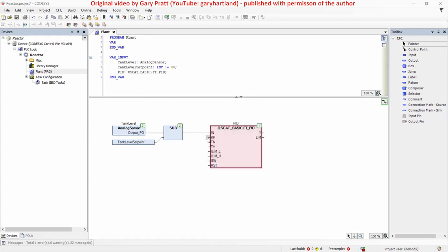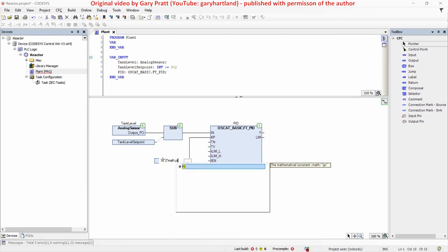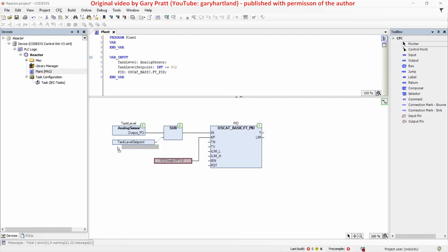For the purposes of this demo, we will use a tank that takes 10 seconds to fill at full flow rate. Since the tank is a pure integrator, it represents a pole at 0 Hz and will have a gain of 1 over 2 pi f. For a 1 Hz control loop, we will want the proportional gain to be the inverse of the tank. That would be 10 times 2 pi times 1 Hz. For now, we'll leave the integral and the derivative disabled.